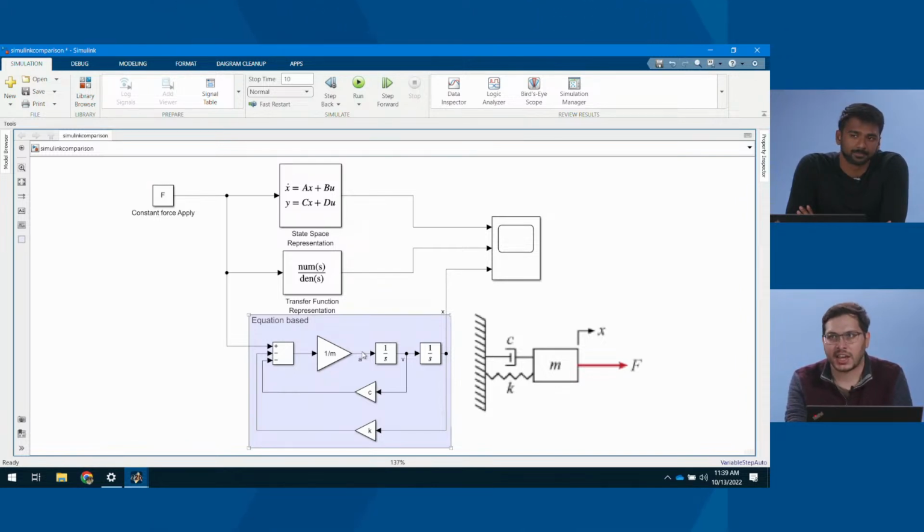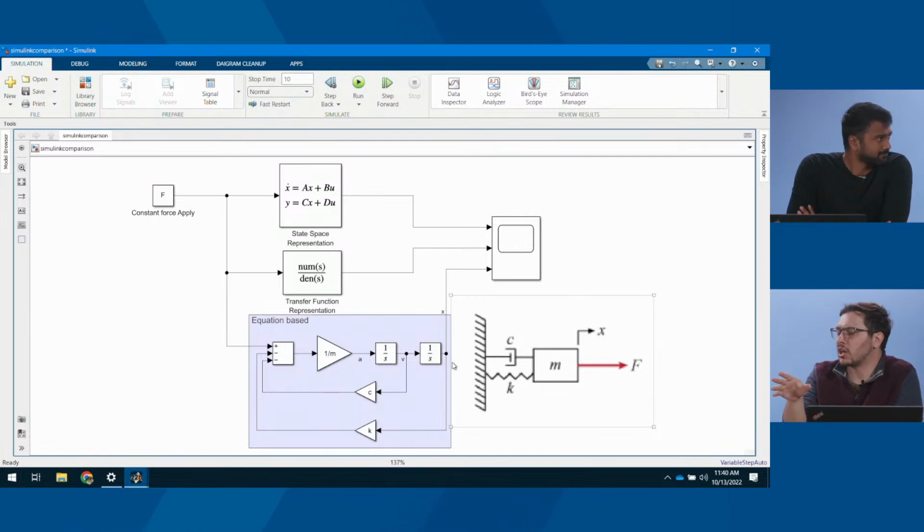There's a lot of things that can happen when you're trying to take derivatives, especially multiple derivatives. If I solve for position and take a derivative to get velocity, that's probably fine. And if I take another derivative to get to acceleration, with the numeric solvers in Simulink it's a lot easier for weird things to happen, and I don't want to be fighting the software, right?